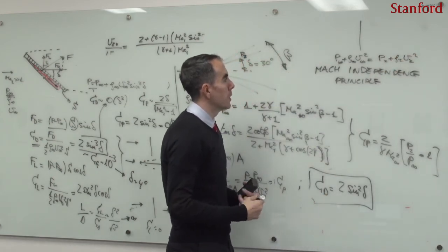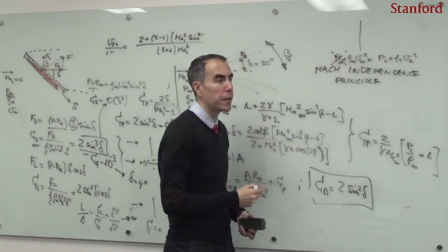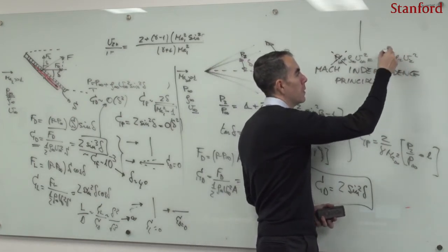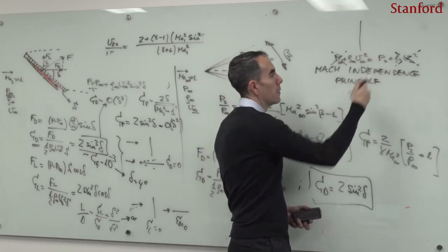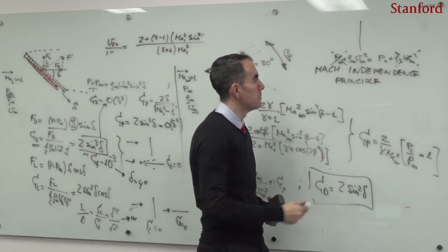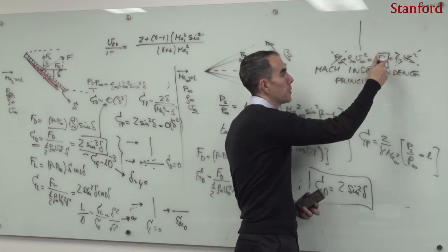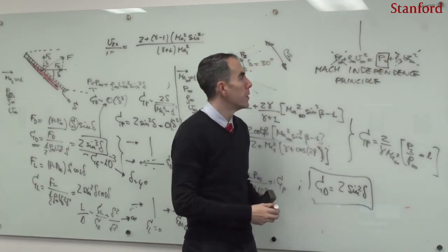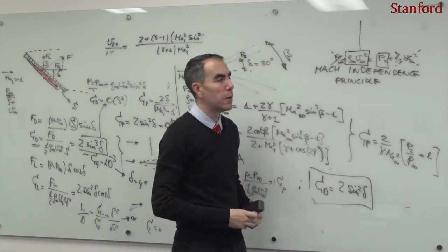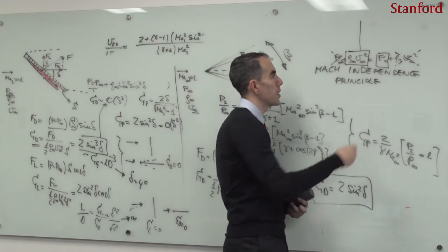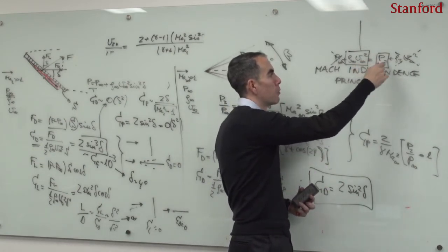As I mentioned in earlier discussions, at high Mach numbers, the static contribution of the pressure upstream of the shock is negligible, and downstream, the kinetic contribution in this momentum flux is actually negligible. So the amount of post-shock pressure that you can build downstream of the shock is imposed by the flux of momentum upstream from the shock. There is only so much pressure that one can build, and the higher the Mach number, the closer these two numbers are.